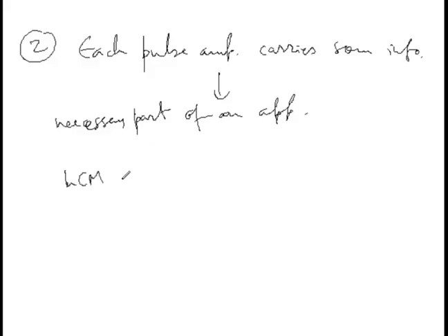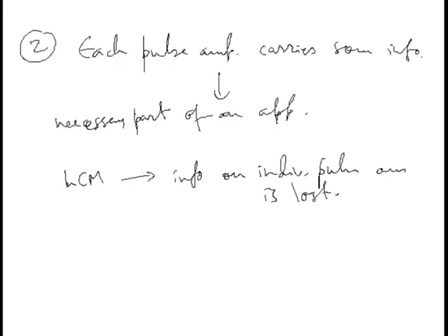This information on individual pulse amplitude is just lost, and all interactions, regardless of amplitude, contribute to the average measured current. Now, because of these two important inherent advantages of the pulse mode, the emphasis in nuclear instrumentation is largely on pulse circuits and pulse processing techniques.